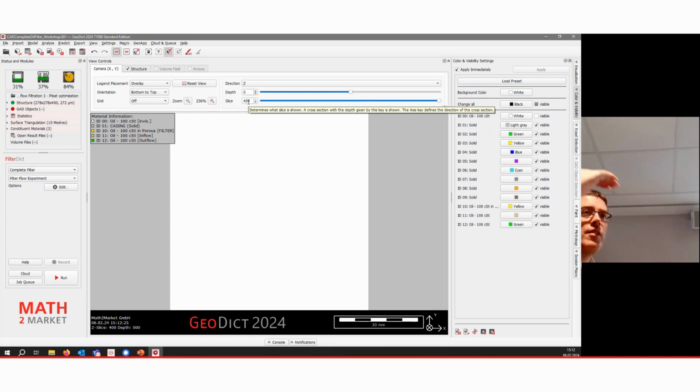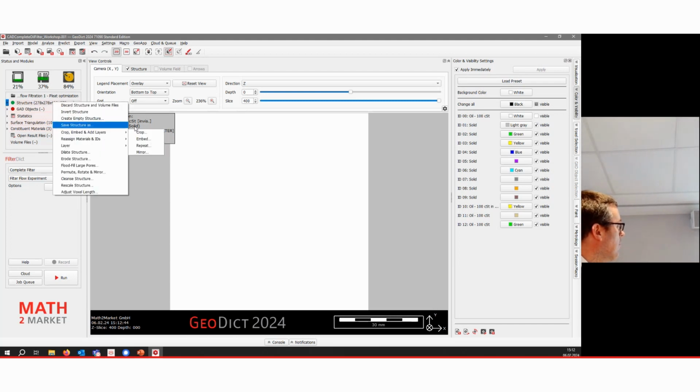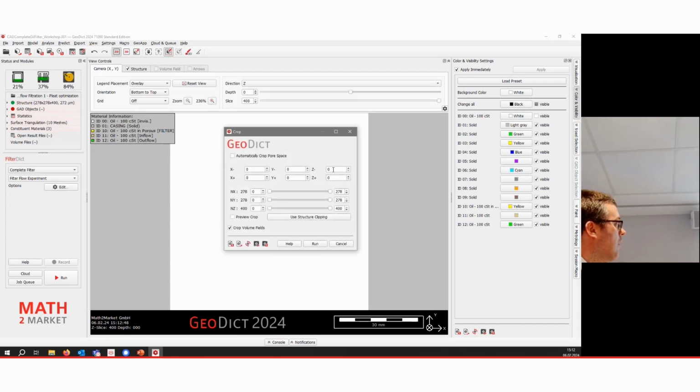So there is actually one slice above that. And at the moment it assumes that all but the inflow has two directions to go from, and it will take the shortest way. So I have to crop the upper layer. Crop, then set, just going one down there. Run.